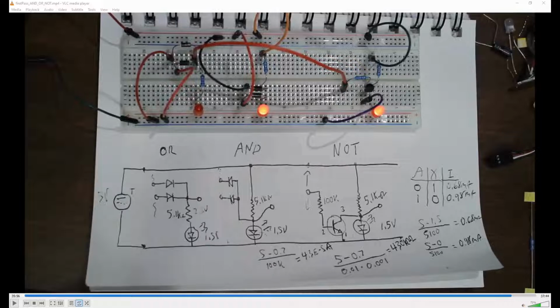We can get by this in a number of ways. We can use an LED with a larger voltage drop. We can gang voltage drops, maybe multiple LEDs in series, or we can do some calculations based on the current that will be flowing through the LED and insert a second resistor in series with the LED. Let's say we wanted to use a red LED still.